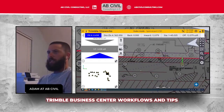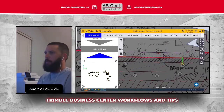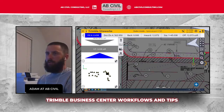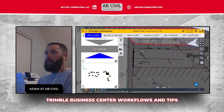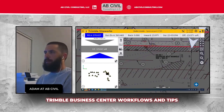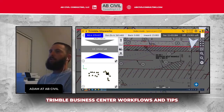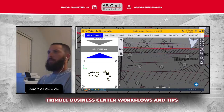One other thing you'll see on here that you probably won't see on many other models is these arrows on the surface that show where the water's flowing. I have to do that manually. Maybe a different week I'll go over how to do that. But if you export a surface in Business Center with these slope arrows turned on, and you export that surface to DXF, you can bring it back into your data collector as a sitemap. So all these slope arrows are part of the sitemap right now.